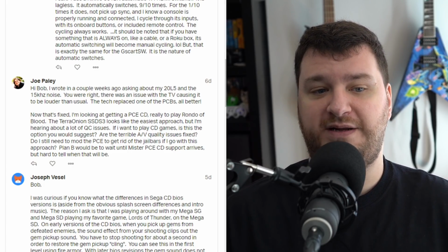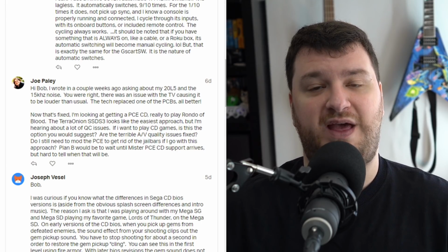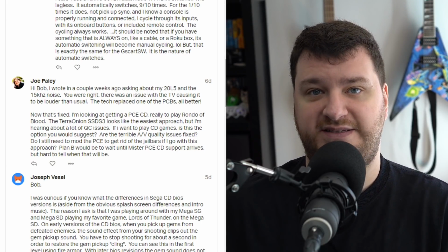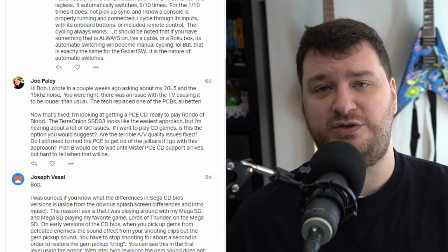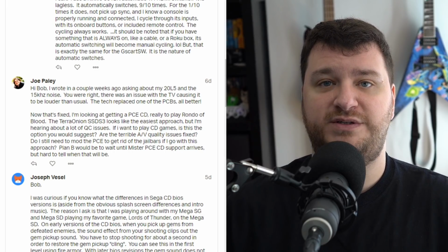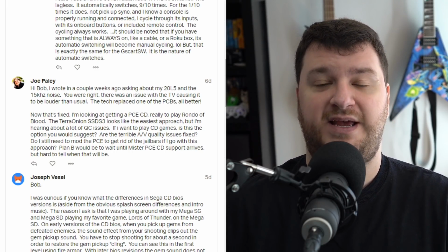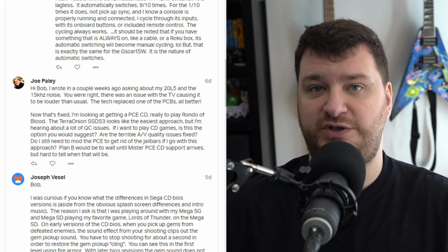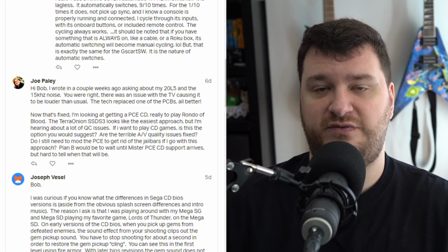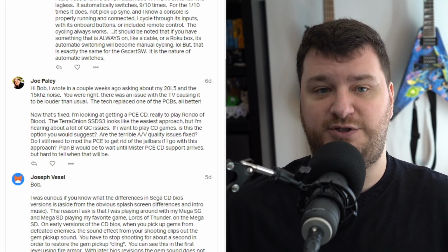But about modding the PC Engine to get rid of the jail bars, that's every PC Engine with every device you use that's analog video. So that's not related to the SSD S3, but luckily it's 2 capacitors that are fairly easy to replace. So if you've ever done surface mount, SMD component soldering, this is a breeze. If you haven't, it should be a fairly cheap mod. And this is one of these things where you could replace the 2 surface mount caps, slap in an SSD S3, and get yourself a great solution.